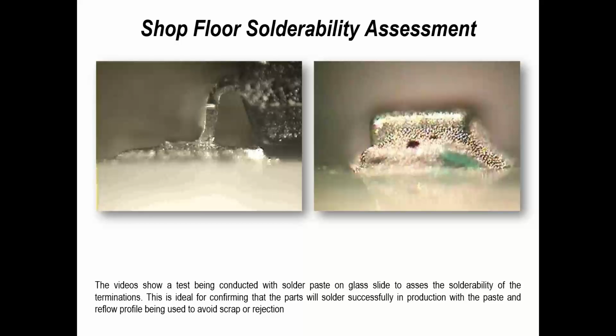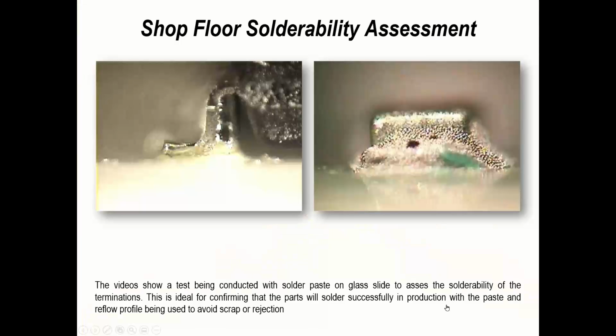Now, just to show you a couple of video clips, what you're looking at here is an SO package. The solder paste is reflowing, and you can see how it's wetting the side of the pin and it's actually wetting up the back of the pin. So again, in that example, I would say that that would run on a normal assembly process and give you